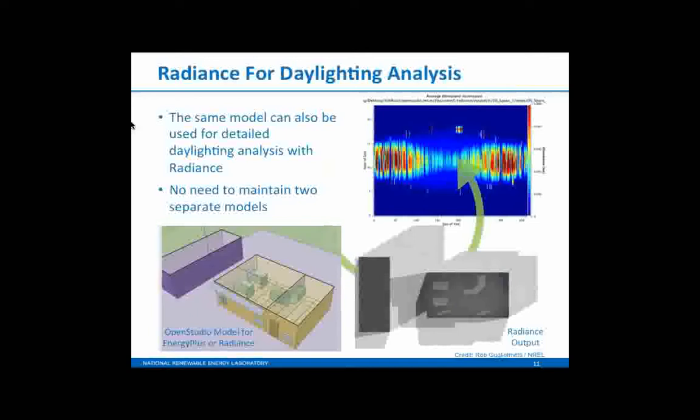So we create objects in OpenStudio so we can say, for example, this thermal zone boundary is just that. It's just a thermal zone boundary. It's not a wall. It actually passes through this bit of furniture in here, which also is not something that you can really define physically in an EnergyPlus model. You can define its mass. You can define people loads and objects, but you can't actually put in physical geometry, things that would actually block or redirect daylight, for example. This is a huge problem.